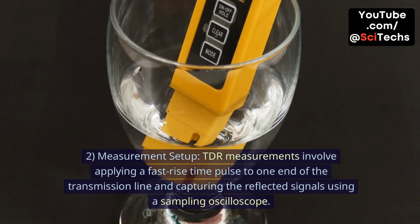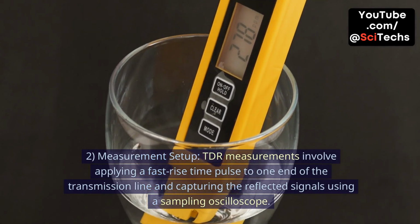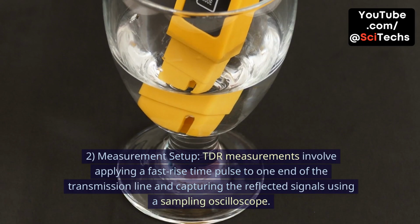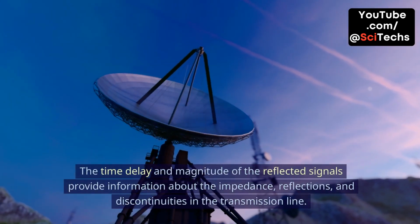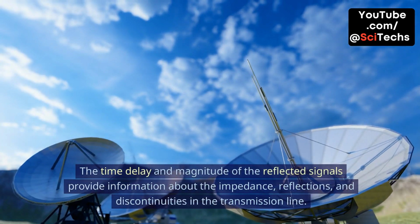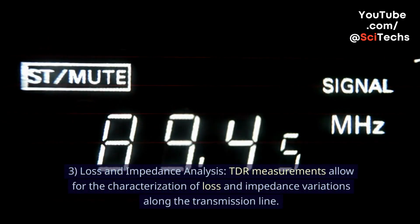2. Measurement setup. TDR measurements involve applying a fast rise time pulse to one end of the transmission line and capturing the reflected signals using a sampling oscilloscope. The time delay and magnitude of the reflected signals provide information about the impedance, reflections, and discontinuities in the transmission line.